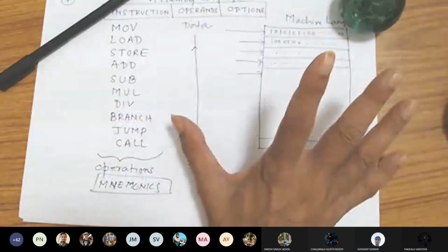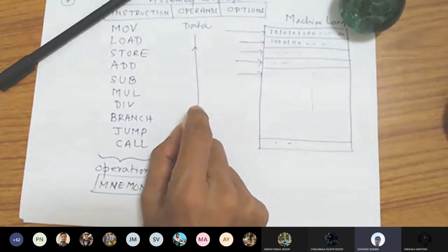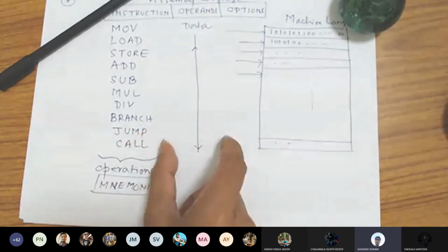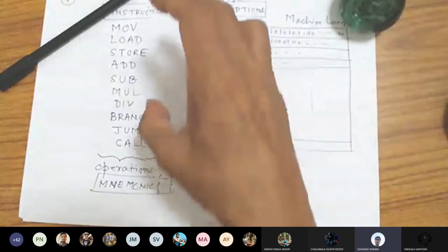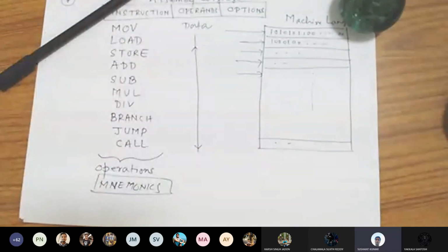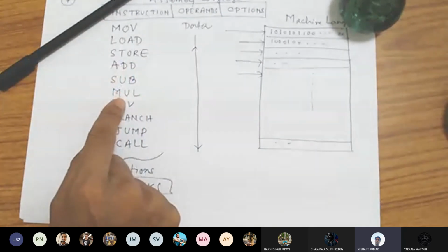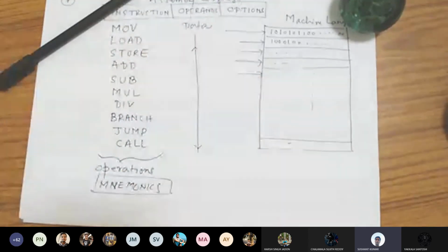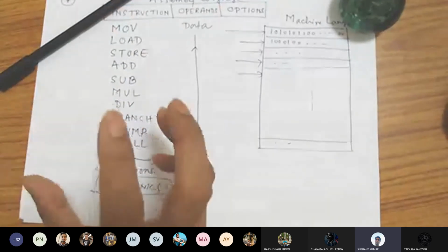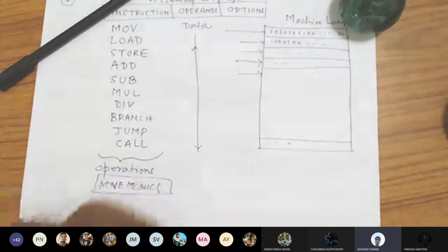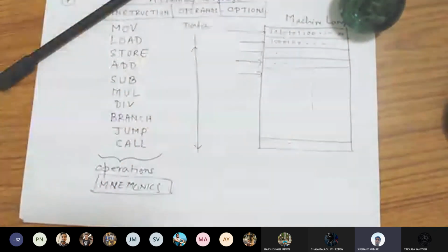Parallel lines are not concerned. The primary concern is how we make the units work. Whether the unit is a 1-bit unit or an X-bit unit is irrelevant here. If the number of units increases, how do you design the circuit? That is the concern. You will not face any difficulty if I change the requirement from 32-bit to 64-bit. Do you think that it will be difficult? No, sir. We just increase the bits of the muxes also. Exactly. Increase the bit width of the input lines and the output line of the mux. That is the only thing. Otherwise, the multiplexer remains the same.